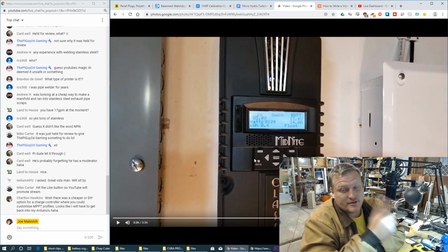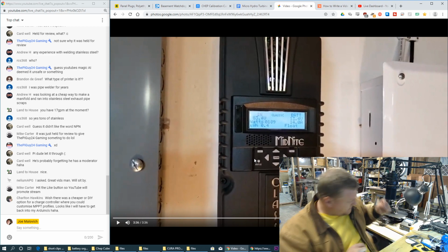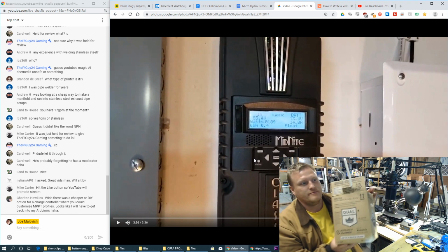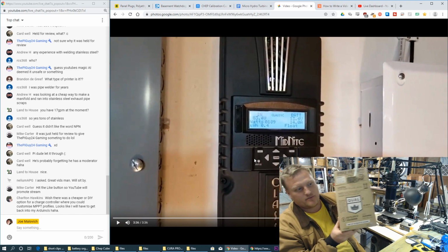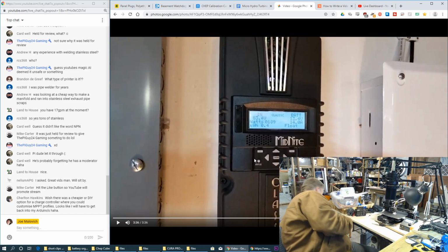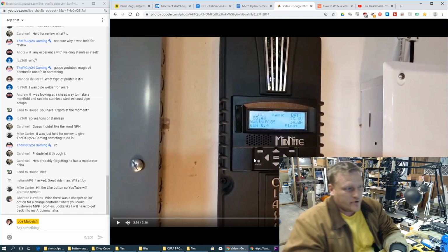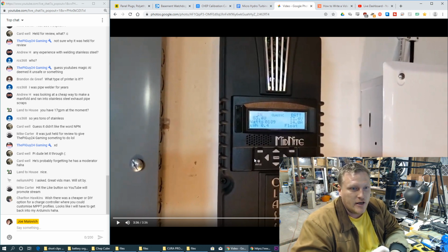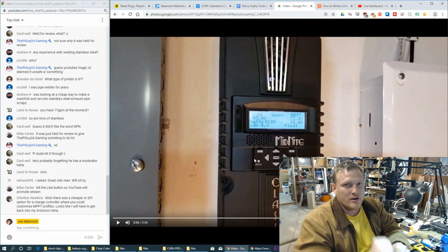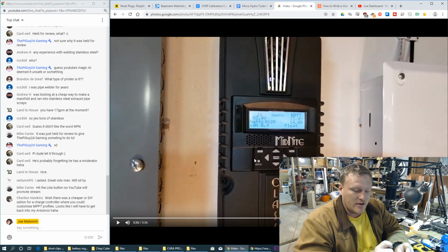So today I went and picked up more acid. This stuff, still a little bit in here. I should probably dispose of it somehow. Baking soda. And I filled up my other battery, and they're both charged up, and I'm letting them kind of equalize, and then I'm going to put them in parallel and let them drain tonight with a load on them, so that tomorrow I can do some actual bulk testing.